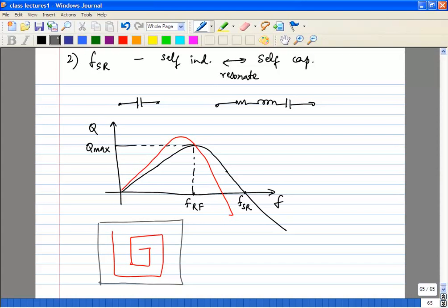Now what happens, so let's say this was on M6, okay. Which layer would you use for the ground shield? Anybody? So you want to use M5, let's say. Okay. So what is the difference between using M5 and M4? Right? Cox is going to get lower if you use M4. So obviously, in the end, you want to use M1. Right? That's the farthest. So your self-resonant frequency of your inductor will be higher. Okay? So let's say you use M1.